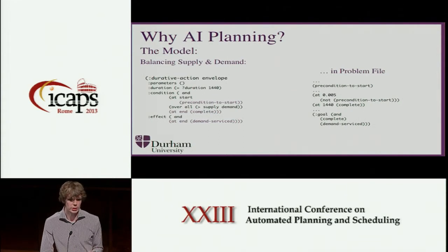A closer investigation of the states considered and search path taken showed that the planner could not distinguish between those solutions which only differed in the loading of the generating units. This means that despite having near identical online-offline schedules, which is the key part of the unit commitment solution, the planner could not distinguish between these states, and the sheer volume of them swamped the state space and prevented the problem from solving. It became clear that this approach was not going to be successful and that a different model should be tried.